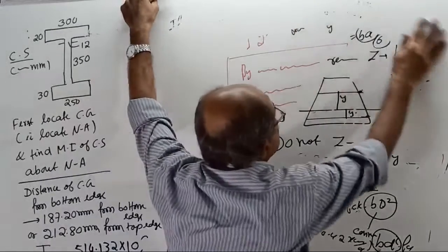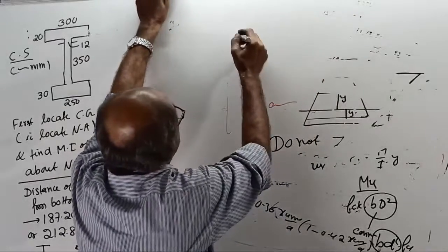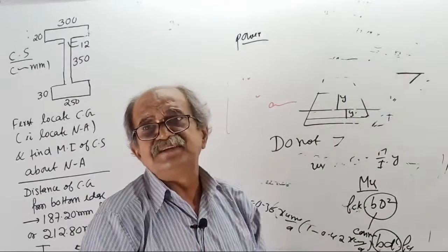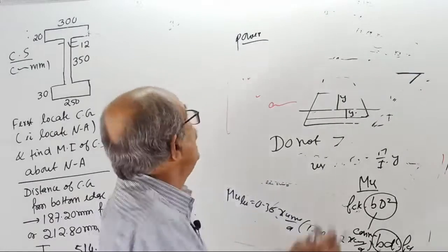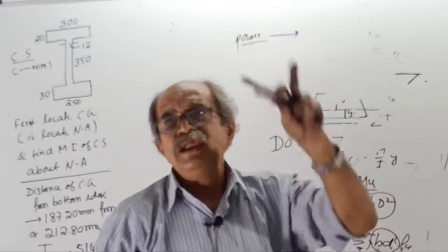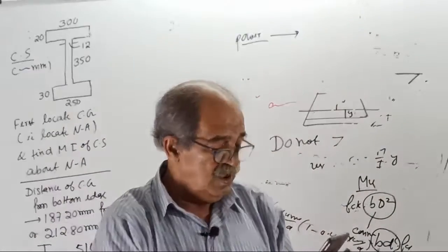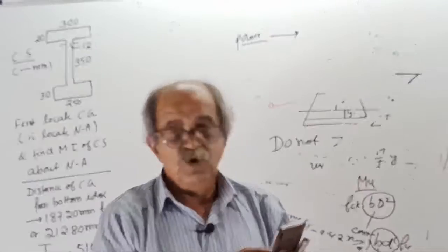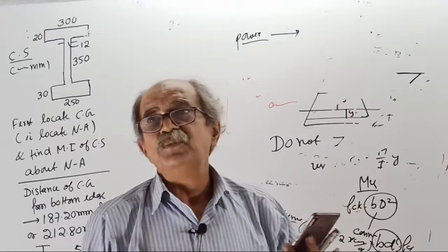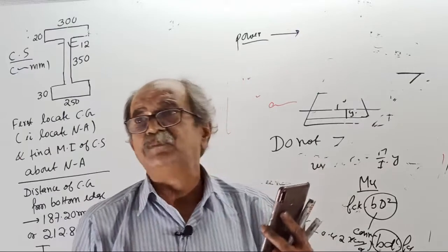Now, next part. Next, I have to go to the most powerful term. The very purpose of this bending stress chapter for practical design, tell me what? The most powerful term for practical design. See, in RCC, you call it MU limit. We know that, MU limit, the limiting moment of resistance for a rectangular balanced section.